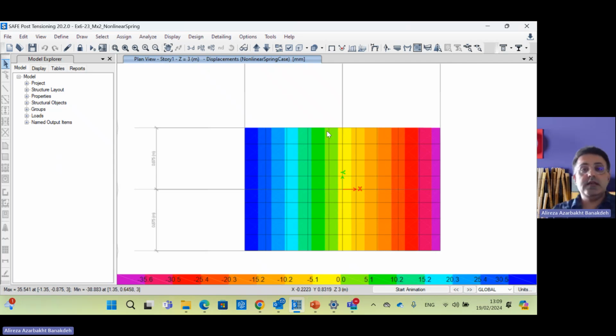And this is obvious because when we don't have those, tension springs are still acting like a glue between the foundation and soil. That's why in the previous case, you had a third of the whole foundation uplifted. But here you have a little bit less than half of the foundation.